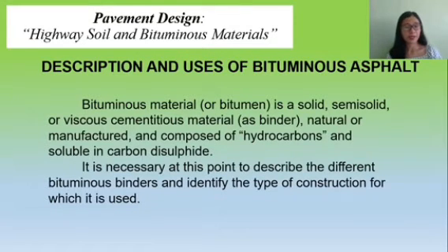So we have here the description and the uses of bituminous materials. Bituminous asphalt. Bituminous material, or what we call bitumen, is a solid, semi-solid or viscous cementitious material, or a binder, natural or manufactured, composed of hydrocarbons and soluble in carbon disulfide.